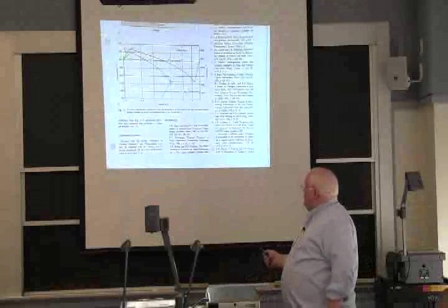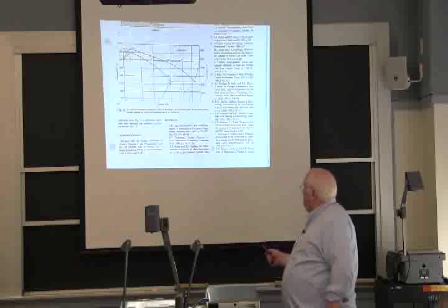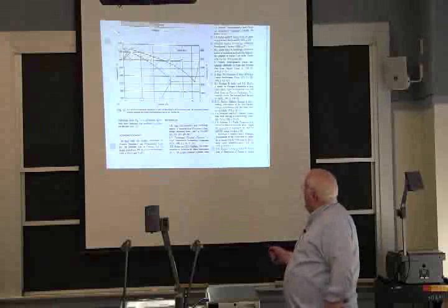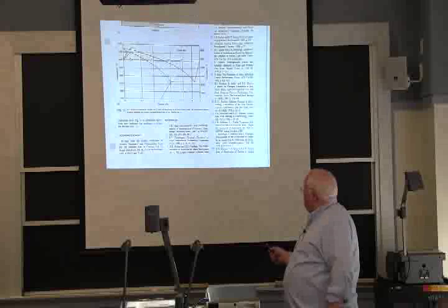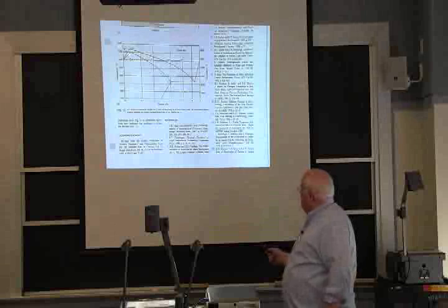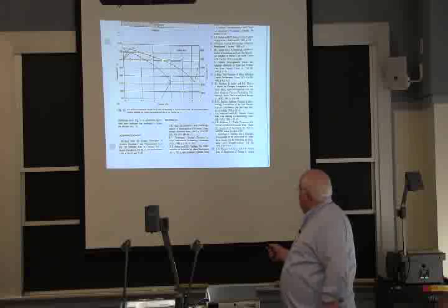So a phase diagram is nothing more than a plot of temperature versus, in this case, carbon. This is the steel diagram at high temperatures. You've got liquid up here. This is your cast iron alloys over here. These are your cast steels up here. This is called the peritectic reaction. We don't have to get into the details of that. But what it shows you is the composition of the liquid is richer in carbon than the composition of solid.